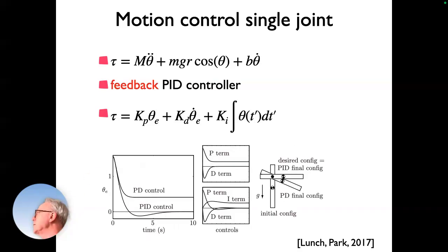We'll come back to that. So here are examples of this acting. For instance, your PID controller will make your error nicely zero under some circumstances, and whether it overshoots or not depends on the parameters you chose for the controller. You see an example.